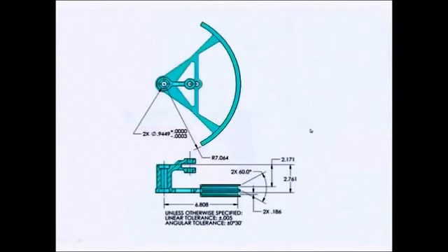The original drawing looked like this. I've redrawn it, cleaned it up a little bit. But they had this radius of 7.064 directly toleranced. In other words, the plus or minus 5 down here applied to the 7.064. The trouble is we don't know where the center of the 7.064 is. You might guess that it's in the center of these bearing pockets, but there's nothing on this drawing to tell us that.